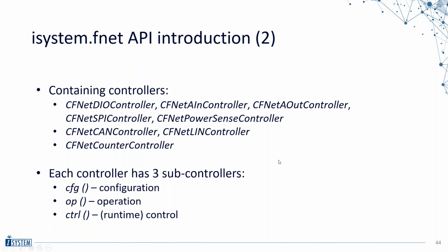Each of these controllers has so-called configuration subclasses, meaning the static configuration of the CAN boxes. The operation subclass means looking at the complete structure inside winIDEA. We can have several add-on modules connected and combine them for the trigger system, etc. And there is so-called runtime control, meaning that at runtime, while we are executing, we can inject CAN messages, and we can change the digital outputs, analog outputs, and so on.